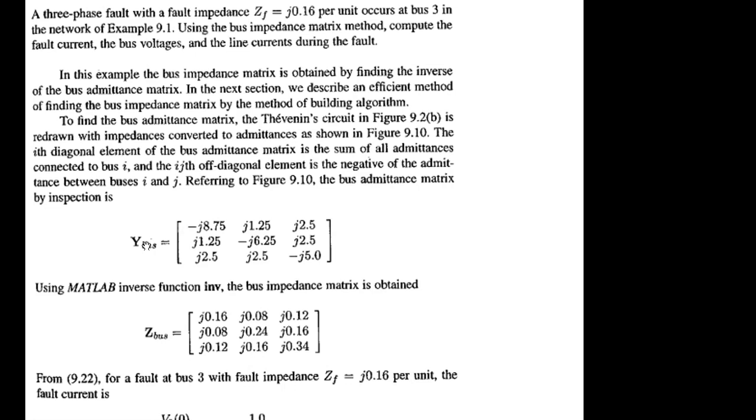So if you have been given Y bus, actually from where can you get that Y bus? Recall from where we can get the Y bus. Yes, sir, we learned it at the very beginning, sir. Okay. If you have been given the single line diagram, you can generate Y bus by the inspection method, right? By the inspection method, you can generate it based on the KCL concept. You have to apply KCL equations to generate your Y bus: the self admittance, mutual admittance, Y11, Y12 like that. So if a single line diagram is given, you can generate Y bus.